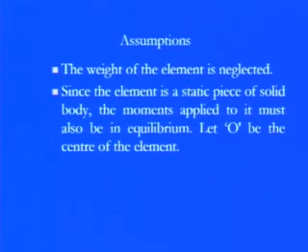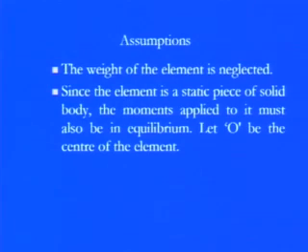But to maintain the equilibrium position of the object, certain assumptions are always there. If those assumptions are applied, then only we can say that yes, this object is well maintained under the equilibrium conditions, and whatever the forces or moments are applying, they are well set up within the object. First, the weight of the element is neglected. We are not considering the weight here, because if we consider the weight, due to the gravitational acceleration there are some more stresses, and because another force application is there along with the weight, a non-uniform stress distribution arises,